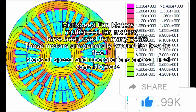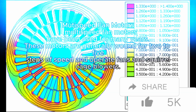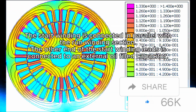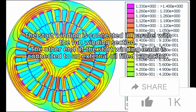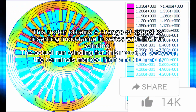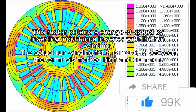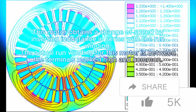Multi-speed fan motors. Multi-speed fan motors have been used for many years. These motors are generally wound for 2 to 5 steps of speed and operate fans and squirrel cage blowers. The start winding is connected in parallel with the run winding section. The other end of the start winding leads is connected to an external oil-filled capacitor. This motor obtains a change of speed by inserting inductance in series with the run winding. The actual run winding for this motor is between the terminals marked high and common.